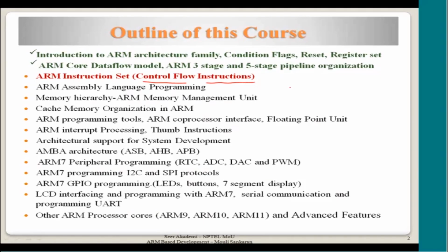Pay attention to this because it has to do with the program counter. These instructions are going to modify the value of PC, which is register R15. Anything that touches this register we need to be careful about, otherwise we will be taking the program to some unknown location. When you are writing a program using these instructions, the assembler takes care of most of it, but you should understand what is exactly happening and which instructions the assembler or compiler generates.